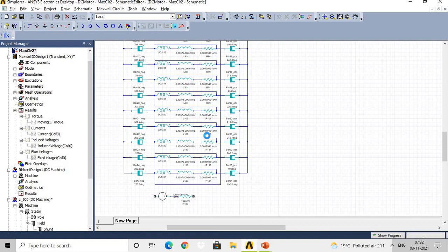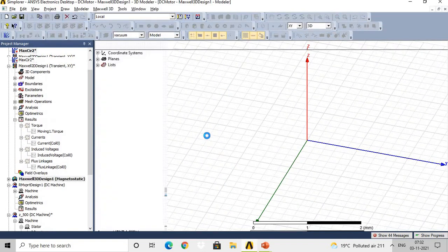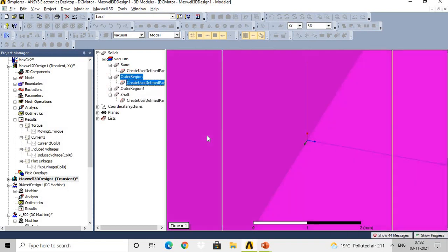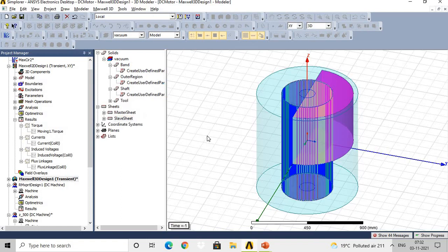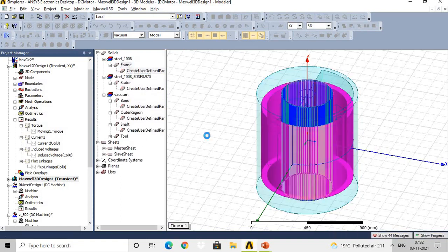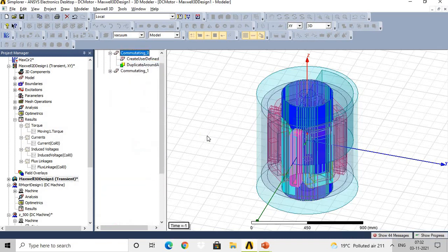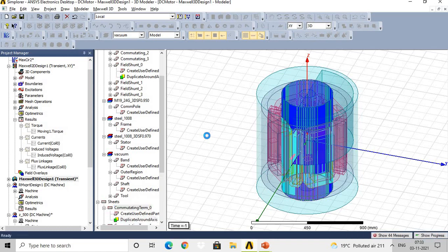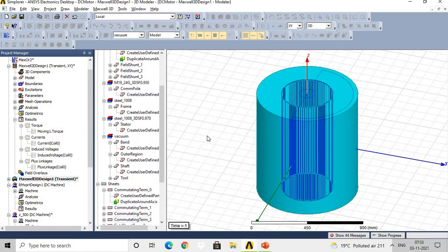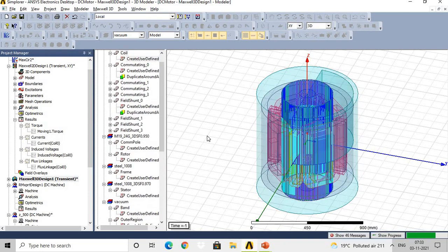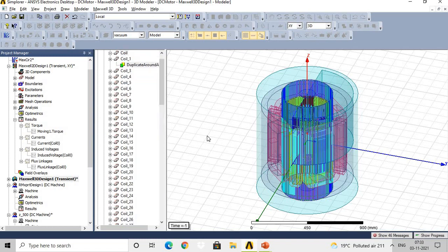Once the analysis is completed, we can go through the total design sheet, then the performance curves of the machine, then the quick report. Then you can convert this design into the Maxwell 2D and Maxwell 3D model. By default it will be converted into the quarter portion or half portion through certain settings. You can make your entire model a Maxwell 3D model, but for the information about the settings and the analysis of the 2D and 3D models,